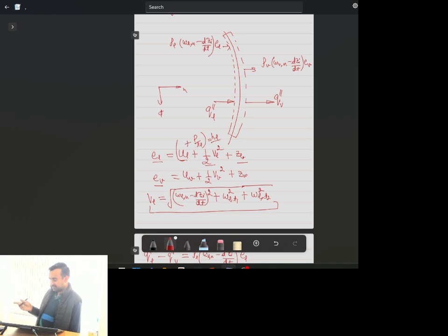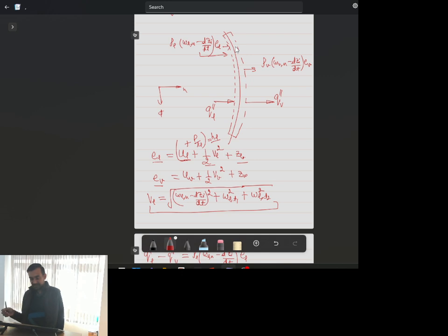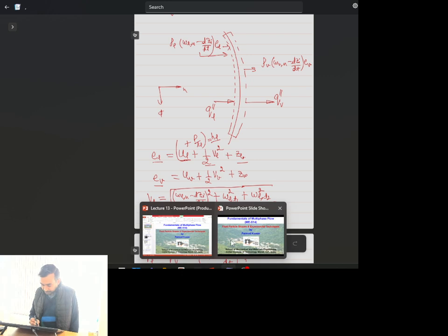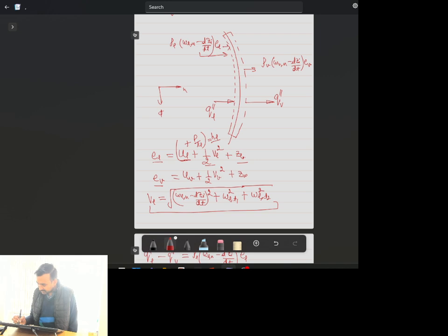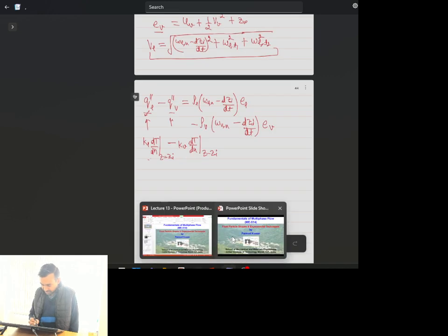So you have to make one correction: instead of writing this total specific energy as internal energy, you have to write it as enthalpy. Why enthalpy? Because we are considering that in this control volume, this liquid mass is entering and coming with some energy. So when it is flowing, then along with the internal energy, it will have flow work also associated with it. Is this point clear? Then this is the correction. Now let us talk about the remaining things.